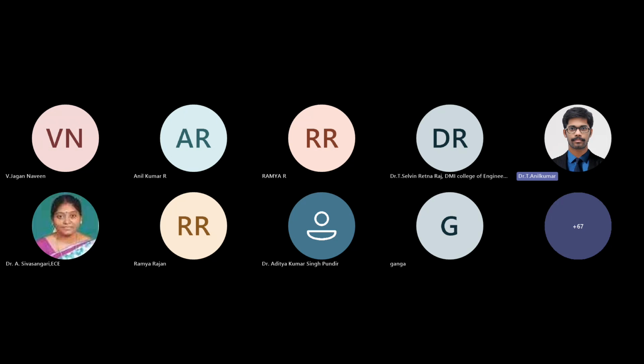Ma'am, in 65 nanometer technology, how can we increase the processing speed? See, as a designer, we can increase the speed by using circuit design techniques. For example, we have seen this skew design, in which we are not taking the output from the extreme output, rather we are using intermediate signals for the inverters. So the signal doesn't need to propagate through all the stages.